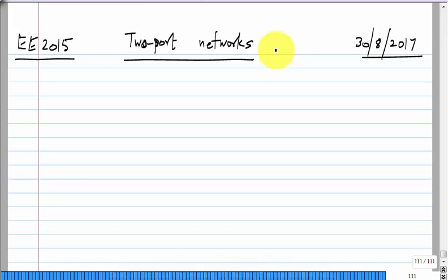Discussing two-port networks, that is, linear two-port networks, two ports which have linear components inside, resistors and controlled sources and so on. And we saw that because there are two voltages and two currents, we need four parameters, four numbers to describe the behavior of this. Okay. So you can think of it as an extension of a one port or a two terminal element where a single number can describe the behavior, right. When you have one port with only linear components inside, all you need to know is its resistance or conductance.